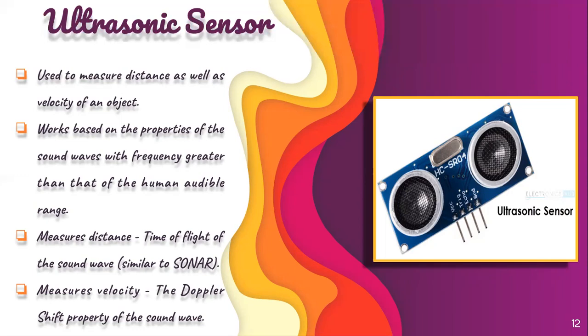Calculate the distance between the sensor and the object. The sensor measures the time it takes between the transmission and the receiver. This calculation is d equal to half into t into c, where d is the distance, t is the time, and c is the speed of sound, which is approximately 343 meters per second. Ultrasonic sensors are used as prime proximity sensors. They can be found in automobile self-parking technology, collision safety systems. Ultrasonic sensors are also used in robotic obstacle detection systems as well.